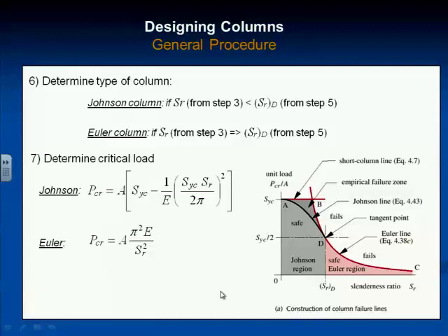So, it depends on the circumstances. A bridge, big safety factor. Some safety factors are legislated by law. That's redundant, isn't it? And elevators, good example. I can't remember the number, but it's big. So the state says you design an elevator, you must have a safety factor of like 4 or 6 or some number like that. Don't quote me because I don't remember the number.